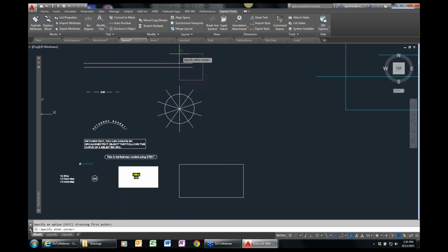Just going to say I want to stretch from this, and it will leave this magenta box on your drawing so you can see what you're selecting. So I want to stretch this stuff here inside the box, and I want to stretch that stuff. I'm just going to accept that. And let's say I just want to stretch it over some distance, and you can see that both the lines and the box are stretched. It can save a lot of time, avoiding deselecting a whole bunch of stuff or doing multiple stretches, any of that type of thing. So that was a great tool.